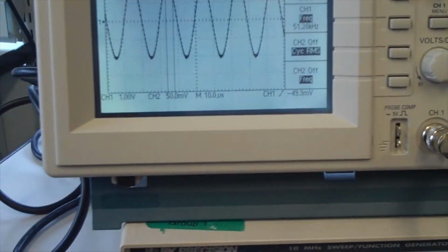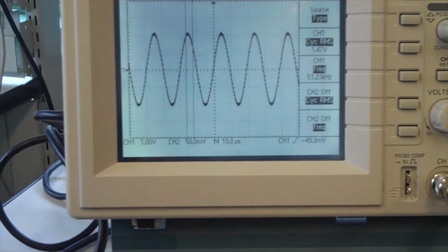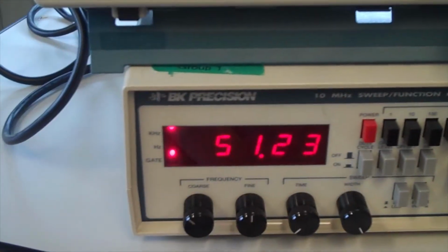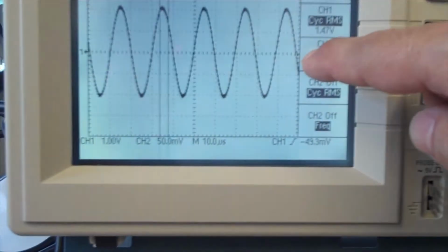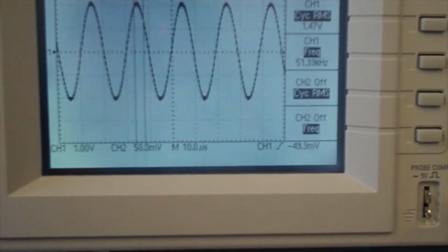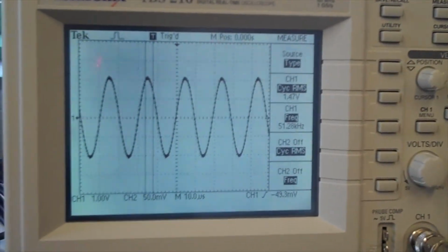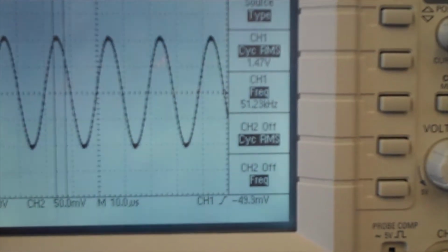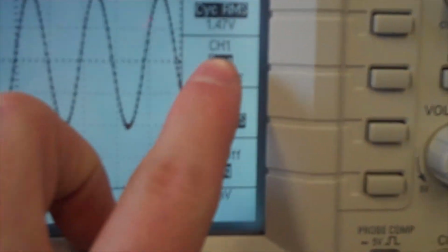You're going to be finding omega 1 and omega 2. To do this, you decide which direction you want to go. Before you go, record the frequency. That's omega naught, the experimental omega naught. The frequency right here is your experimental omega naught.